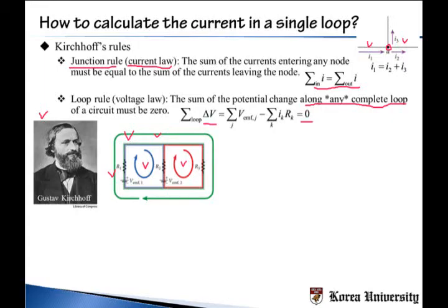In that case, you will go through this EMF device from the negative terminal to the positive terminal, and we learned that in this case the potential will increase by V_EMF. So you have the positive EMF potential in the summation, and then you go through the resistor along the current, and we already learned that it has to be minus IR.